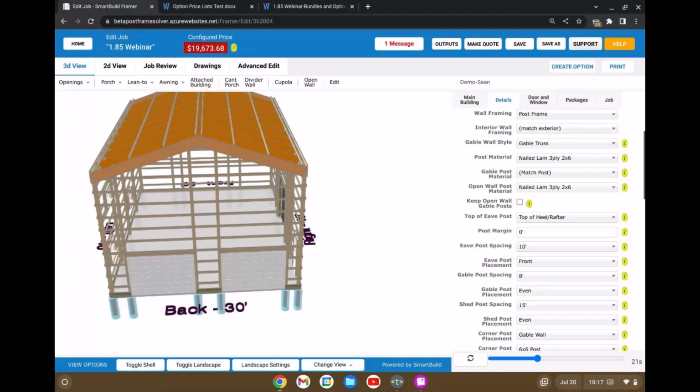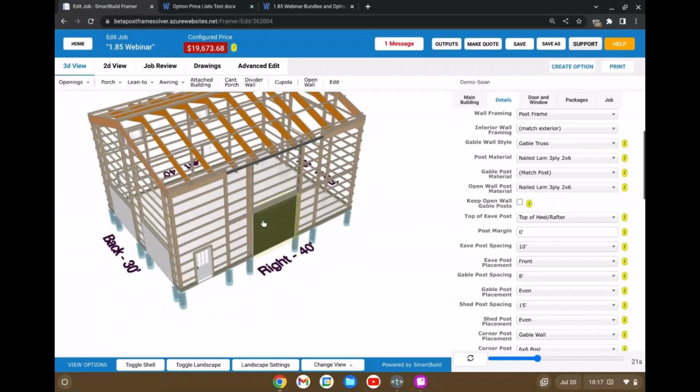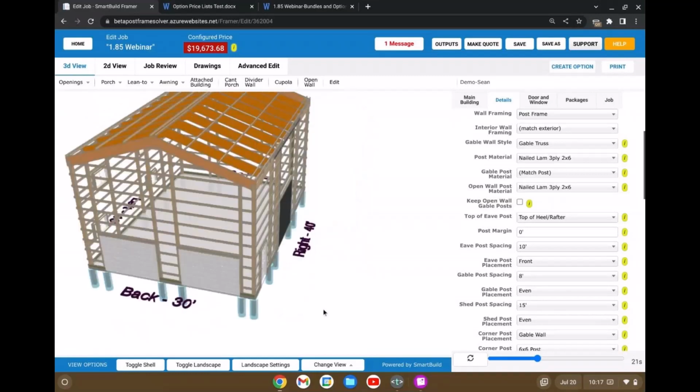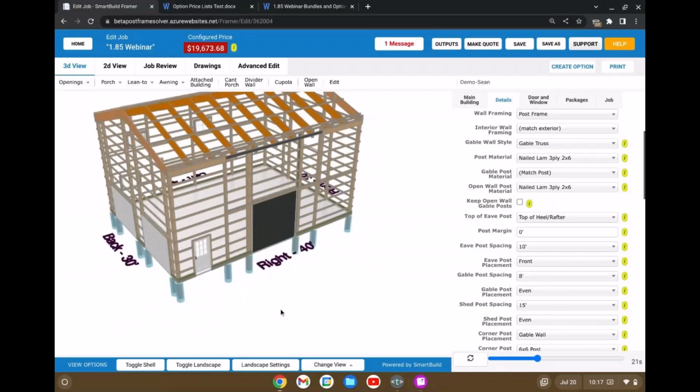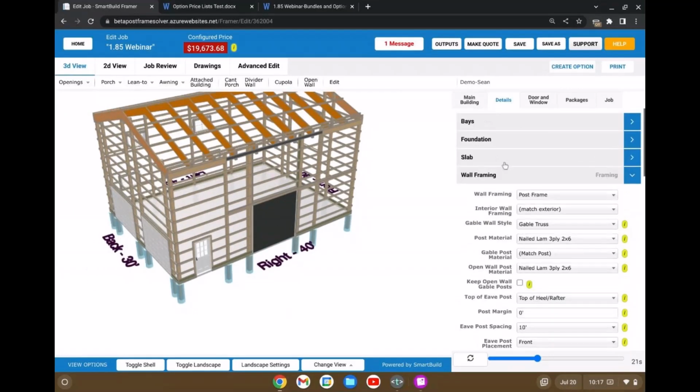So that'd just be for the gables. Would you do something different on the eave? It'd just be for the gables. The eaves have been behaving great because they are tied to the trusses, and that's what we would like to see. Okay. Now on the eaves, if you raise that opening up though, you would still need the posts underneath it, right? Correct. I see now.